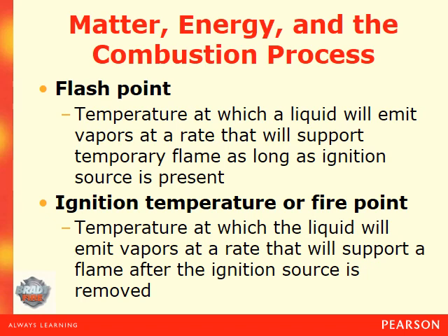Ignition temperature, or fire point, is the temperature at which the liquid will emit vapors at a rate that will support a flame after the ignition source is removed. So that's basically saying diesel fuel, okay? If you take a match and you toss it into an open container of diesel fuel, it will not light because it has not reached its flash point.